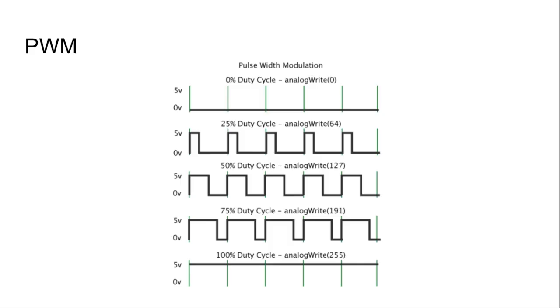The idea is that usually when we connect an LED, a motor, or a stepper motor, we connect capacitors and resistors to control the amount of voltage and the current that drive the LED or the motor. I'm talking about DC motors. However, connecting resistors directly in their circuit for this purpose can dissipate the energy and also increase the heat of the circuit. Another idea that avoids this trouble is to use a signal to drive the LED or the DC motor, and the idea is that it alternates between on and off. Then you will get an average of the total signal.